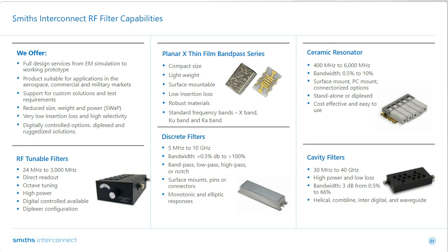The one that we tested, where we showed you the methodology of the test report, actually started to get destructive around 20 watts. That was a narrow band filter. If you had a wide band filter, we could absolutely do up to 50 watts, I'd say. But typically these are low power 1 watt devices.